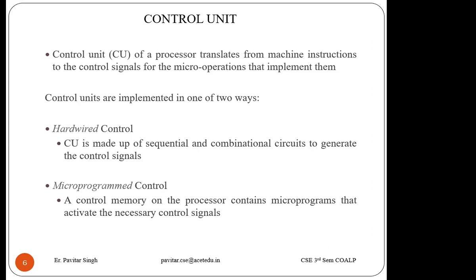That is why this is called hardwired control unit. But in case of microprogram control unit, there will be no such components. Only a microprogram will be written which will generate the control signals. But in case of hardwired CU, these components will help to generate the control signals.